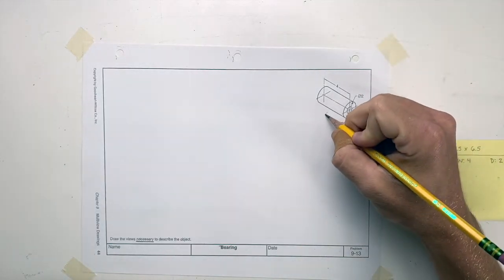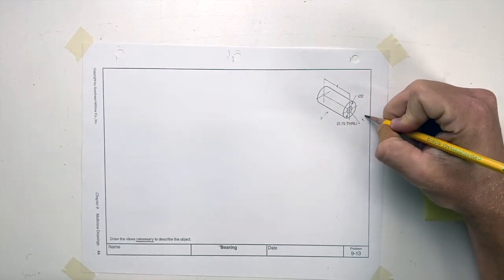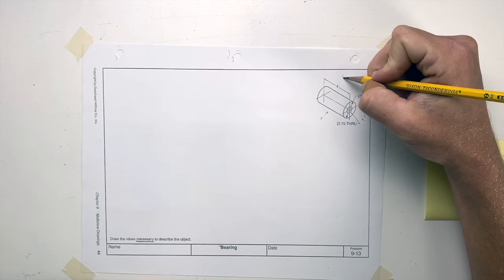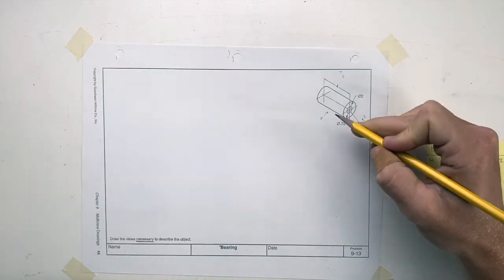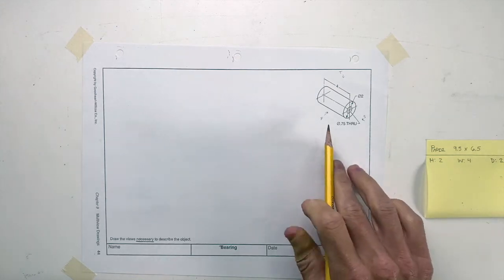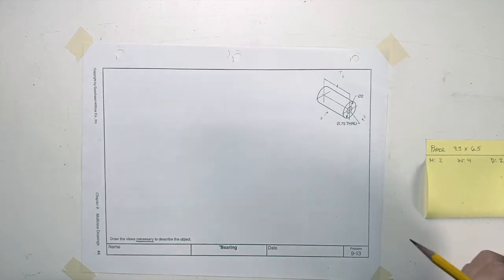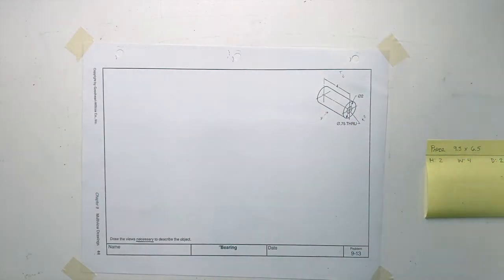If we keep it the same as the other ones and we call this the front, we call this the side, and this would be the top. Well, if you think about the front and the top, they're going to be the exact same. So what we're going to show is the front and the side view, and we're going to eliminate the top view. So that means the spacing for this one is going to be slightly different. We're just going to create a center line going through the entire thing.